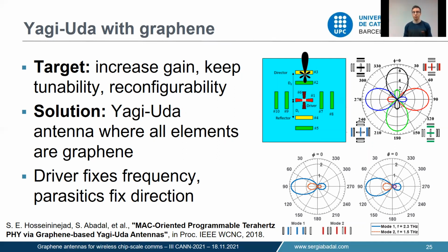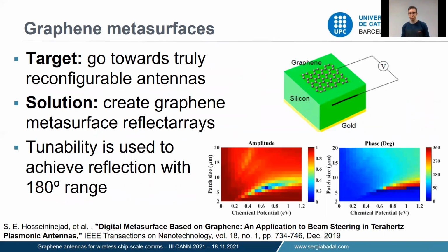And in the picture at the bottom, we demonstrate that you can do that while you are also modifying the frequency of resonance. So if you provide more parasitic elements at different distances, and you select them carefully, you are able to provide this spatial reconfiguration at different frequencies. So you approach joint frequency and beam reconfiguration, which is very, very hard to provide with metallic antennas alone.